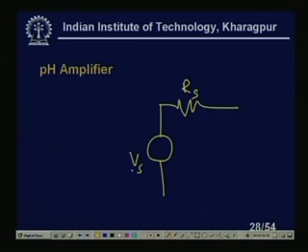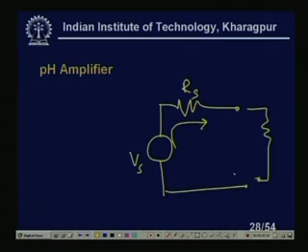right. So, if I try to draw some current through this circuit, because when you measure with some meter, okay, it has some input impedance, is not it. So, a current will start to flow if you connect this one, suppose this is a meter, then what will happen? There will be a large drop across this, okay. So, I won't get the proper measurements.